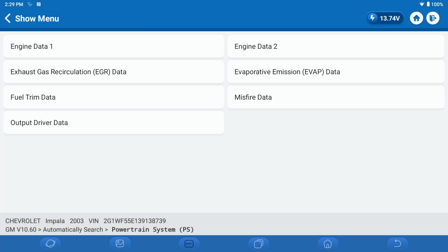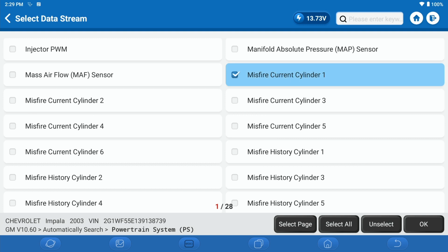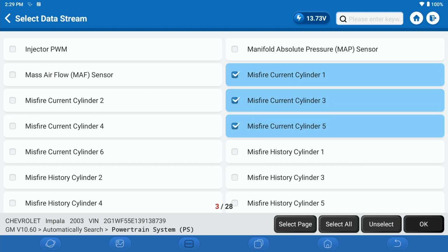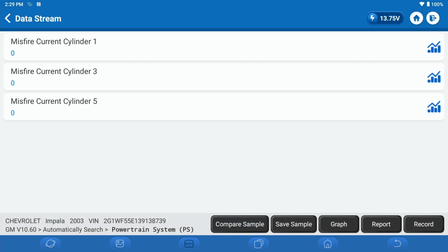Let's see if we've got, that's misfire data. If you look at misfire data, there's all kinds of information up there. You could look at current misfire data. Not all cars have that. We'll just do these up here, just do 3. So you would have misfire data on the system. And looking at it right now, I don't think we'll get anything out of it, but it's something you should do. If the vehicle has misfire data, you should check that. If not, you have to go to mode 6. And mode 6 is up there. It says right now you have no misfire, so we're okay.